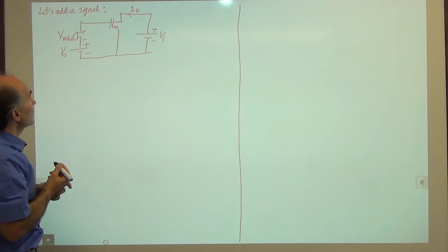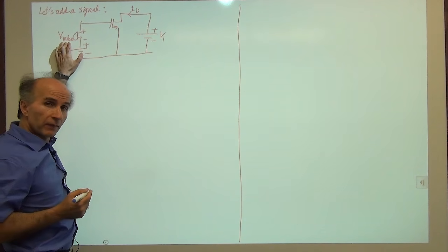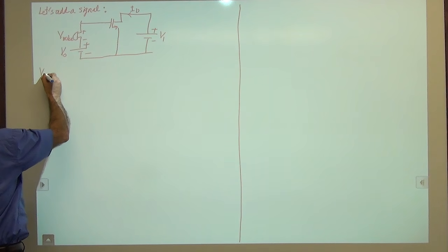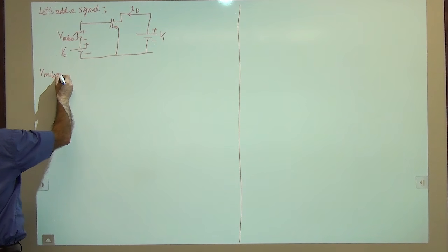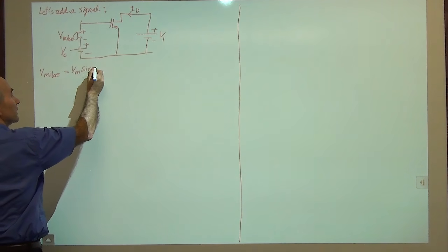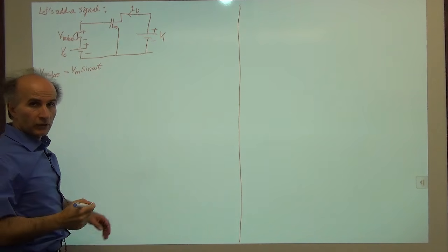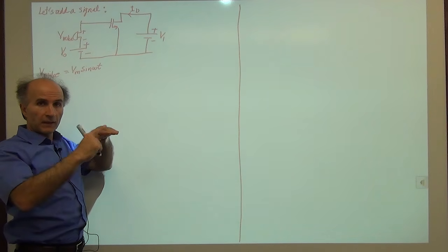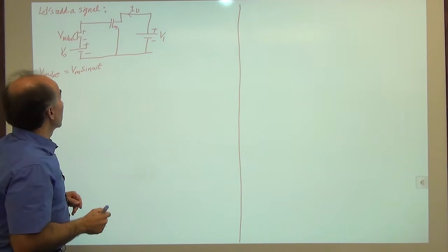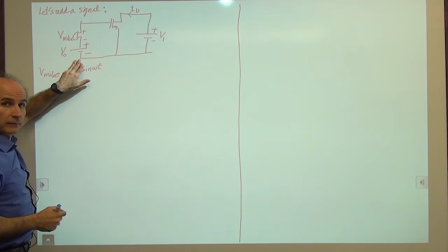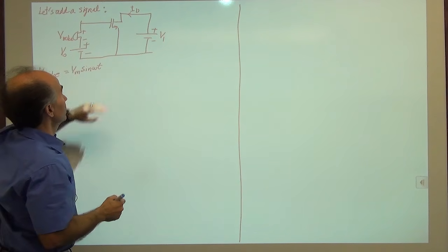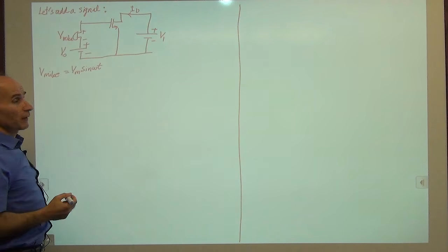Okay, so let's imagine that Vmic is just a simple sinusoid. So Vmic is equal to Vm sine of omega t. That's all. It's a little sinusoid with 0 DC. It just goes up and down around 0, right? But it's added to V0. So this VGS now has V0 plus this in it, right? Okay. So can I find ID?